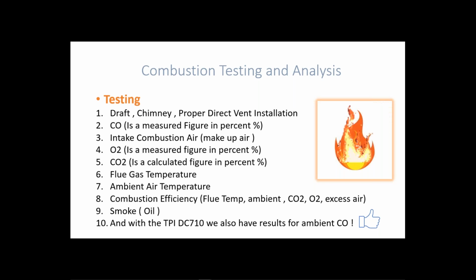I don't really know of any combustion analyzers other than real high-end industrial type analyzers that use a CO2 or carbon dioxide detector or sensor. Most of them are using a calculated CO2 figure. And we take that calculation by knowing what the carbon monoxide is, the oxygen is, and the excess air. And it becomes a calculated figure. We also need to know what flue gas temperatures are. Not only does it help for efficiency, but it also helps to know if we're running rich or if we're running lean.